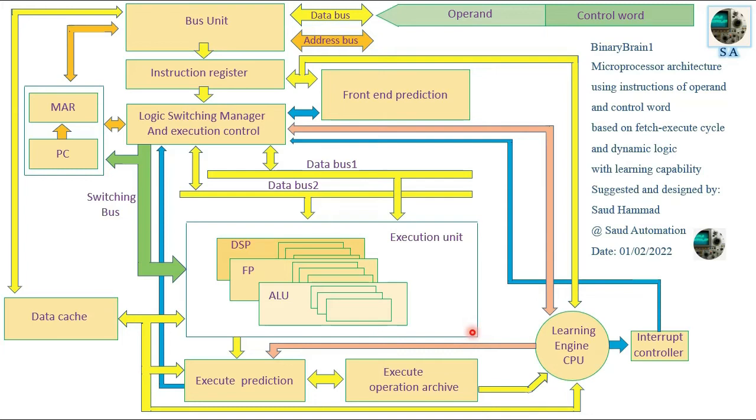The suggested architecture is built of dynamic logic units, and the control word selects and directly enables the execution hardware unit customized for every instruction. So there is no need for the opcode to be further decoded.